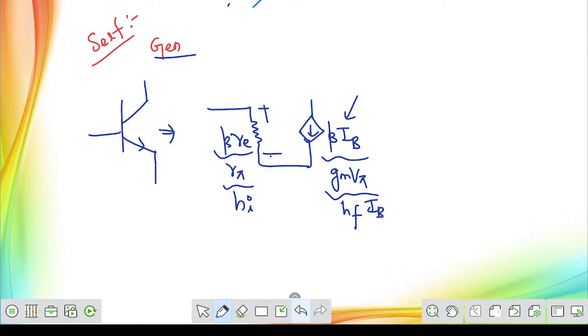That's it. So all these models are equal to each other, sir. No need to memorize all this. Sorry, no need to perform all the methods differently. Remember only one method and approach clearly with that. Draw the equivalent circuit. After that, go to the base terminal. With the base terminal, if they are connecting some resistor, just connect it here.